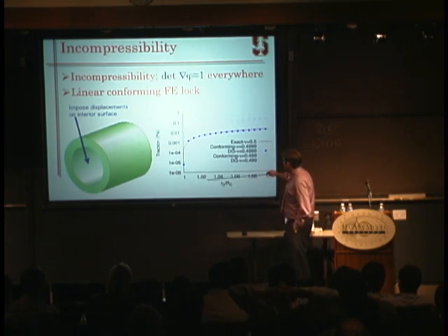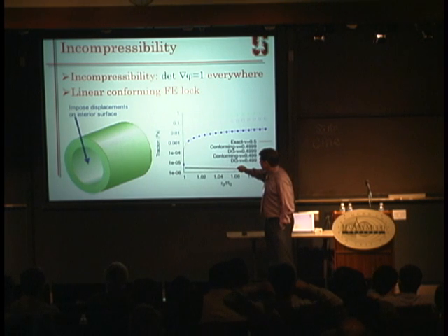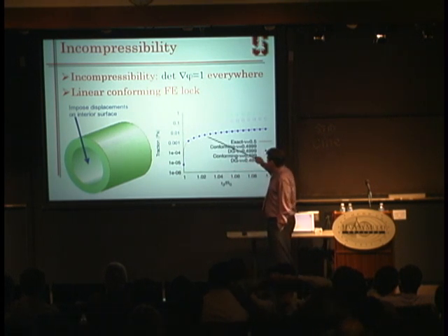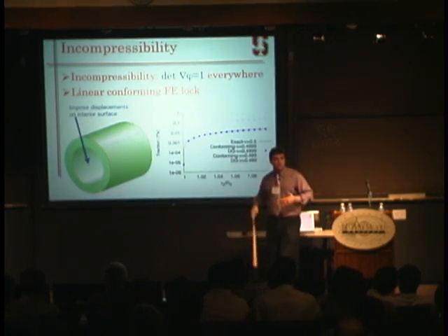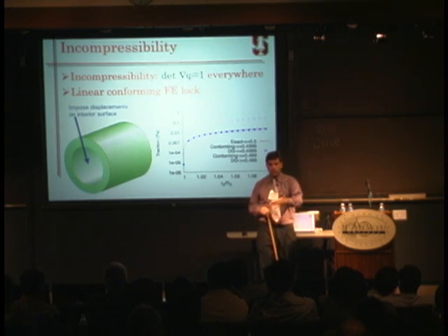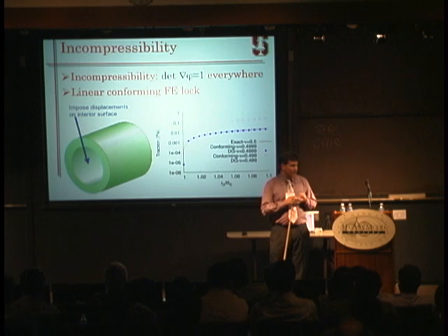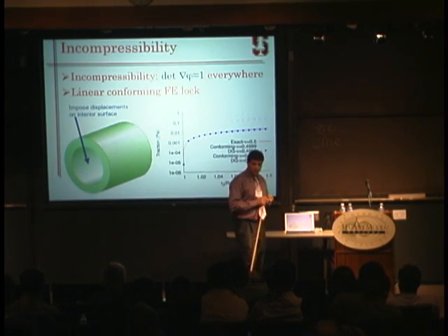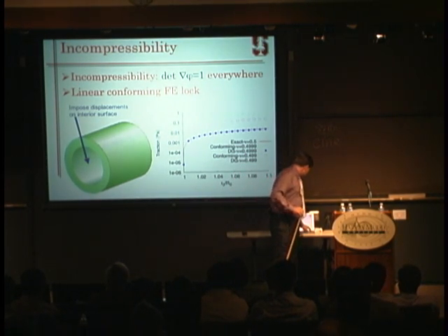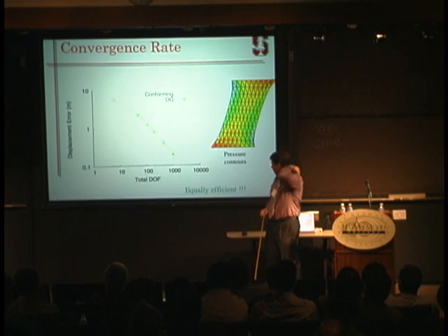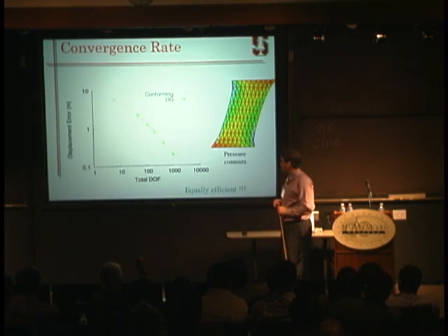However, for the same case with discontinuous Galerkin, as you get more and more incompressible, the traction stays the same. We did not add any more degrees of freedom. We did not have to choose a penalty parameter. So this is very, very promising in that sense. And it's still very cheap. These are piecewise linear elements.